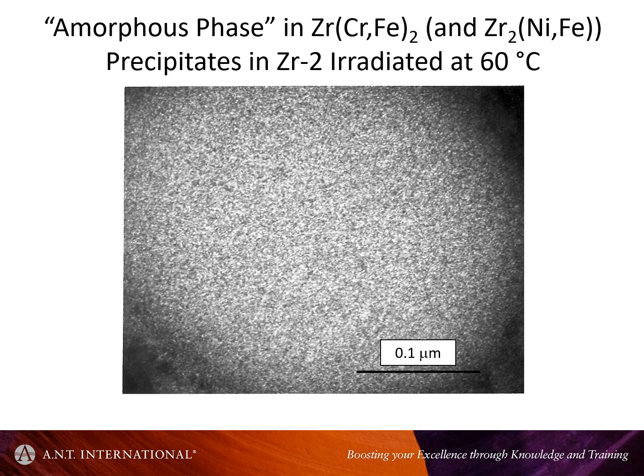And what was observed is for Zircaloy-2 calandria tubes, both the Laves phase Zr(Cr,Fe)2 precipitates and the Zr2(Ni,Fe) precipitates, which I incorrectly labeled Zintl phase. It's roughly reasonable, but strictly speaking not correct to call them a Zintl phase. But there were these other precipitates, and they both became amorphous at low temperatures.